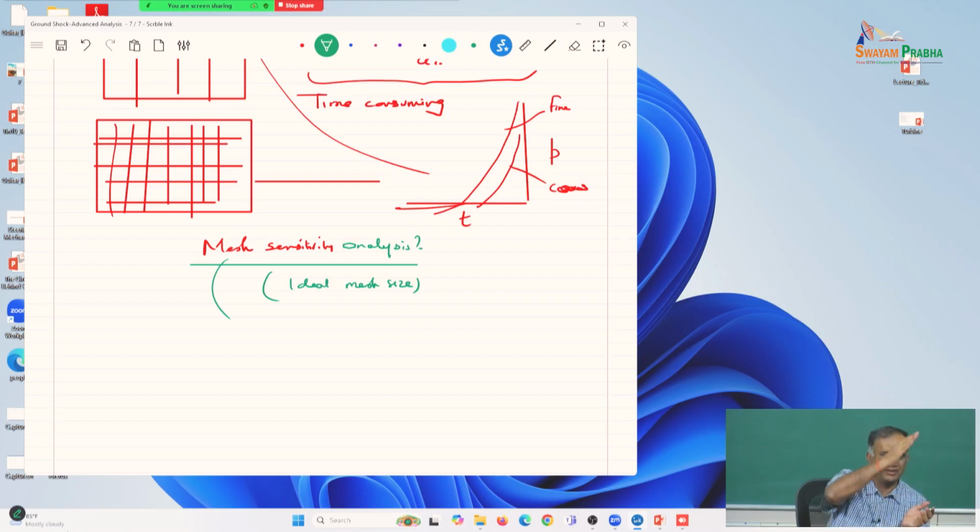You would think that as the mesh sizes keep decreasing, your simulations converge, right? It should converge, same deflections. Doesn't happen because concrete is a complex material. Or even for that matter, except aluminum and steel, which are homogeneous materials, composites and others fall into the range of complex materials.